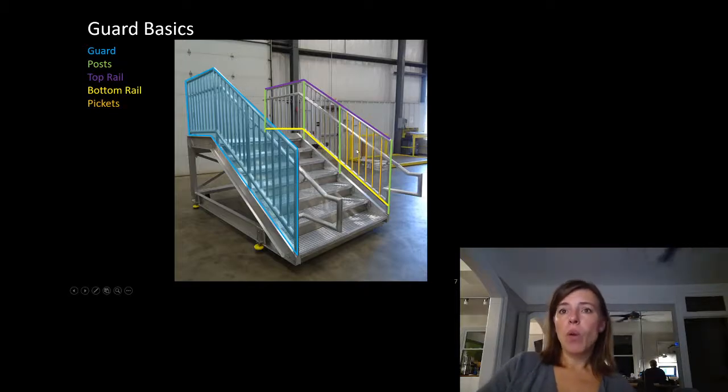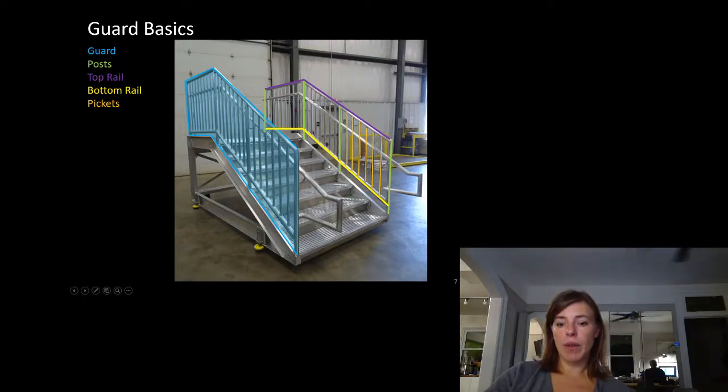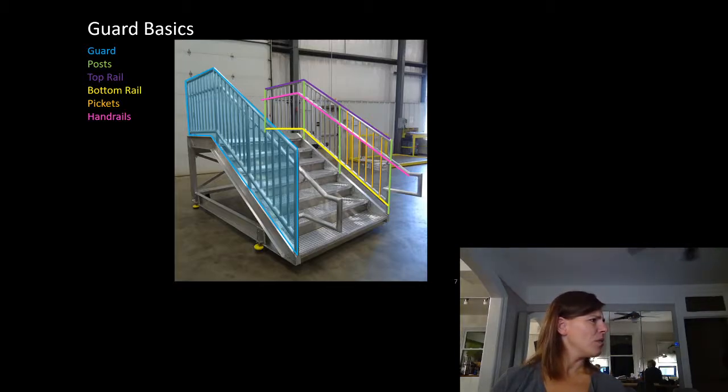Pickets, we would want to look at that 0.5 kilonewtons applied at the midpoint of one of them. And then the handrail, is usually at what, 3 feet exactly? What? The posts? Oh, the handrail, yeah. The pickets can be at whatever space in it. 4 inch, yeah. Sorry, the handrail's at 3 feet, right? Yeah. So 36 inches is where your handrail is, but our guard needs to be higher.